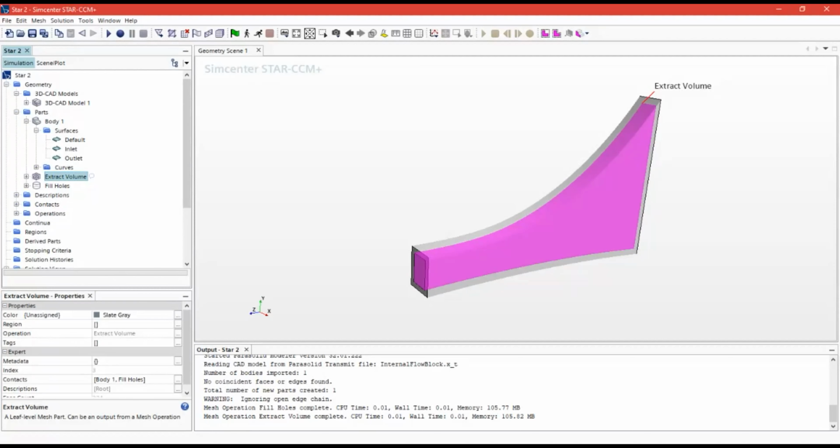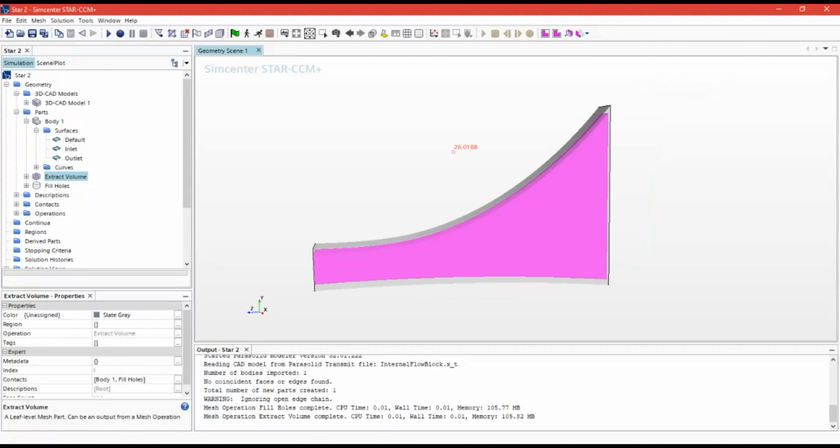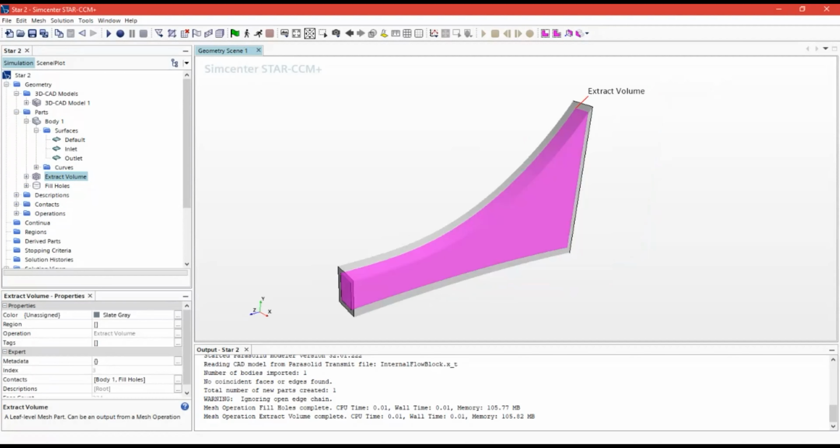Or in our case, we're going to set it up as a stagnation inlet, which essentially means that it acts as though there's a large mass of air, ready to go through the inlet. And the way that we get it to come through that inlet is to set a negative pressure boundary on the outlet side to suck that air in from the stagnation inlet.